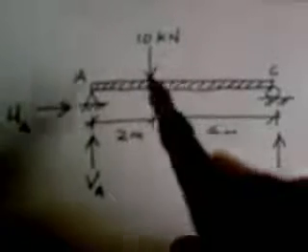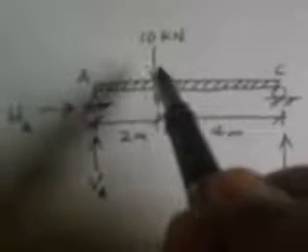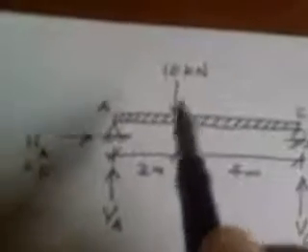Okay, so one thing we need to know is that the applied force is vertical. It means that there is no horizontal force. If there is no horizontal force, there is no horizontal reaction. All the loads that we are using here are vertical loads, so there must be an equal and opposite force for every applied force. Since there are no horizontal forces, there will be no horizontal reaction to resist it.